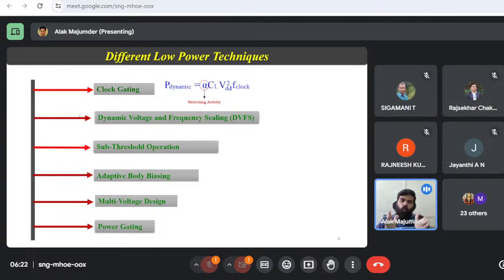So if your core is performance heavy, which means you need efficiency in the speed, you cannot cut down the VDD as per your necessity, because it will enlarge the delay, right? Latency will be increasing. But if your core is power dominant, meaning your design is targeting the power only, not performance, then you can cut down your VDD to the lowest VDD at which your circuit will work.